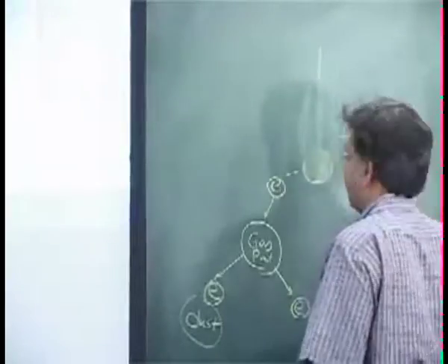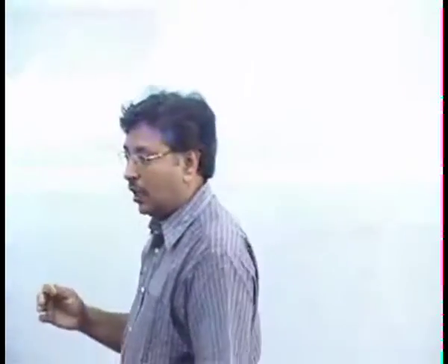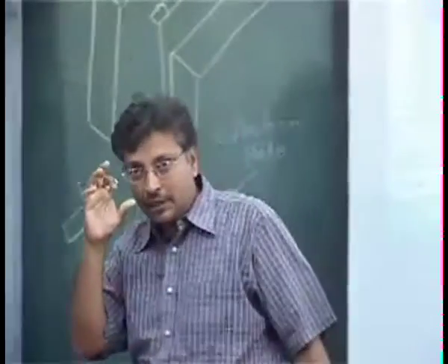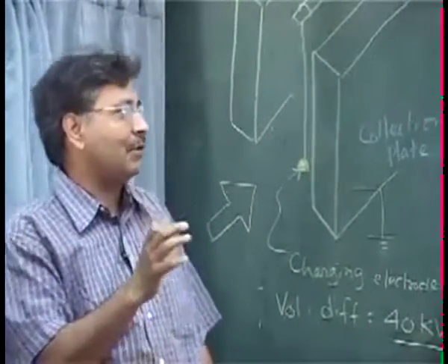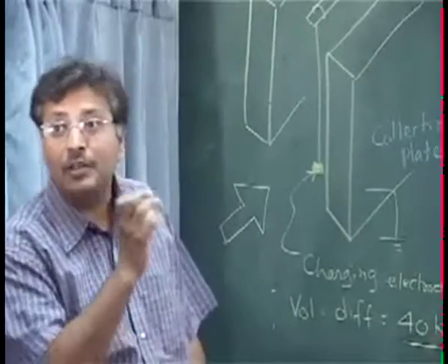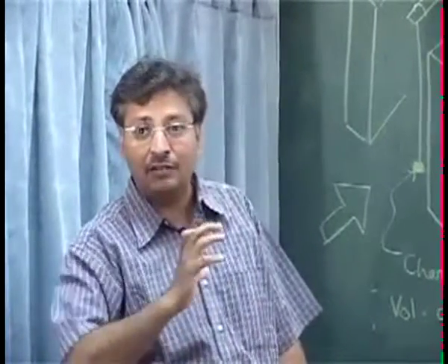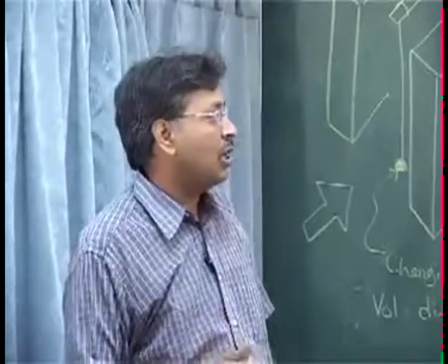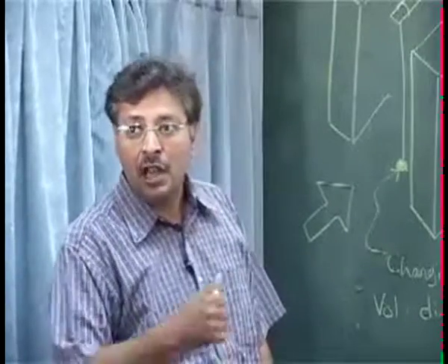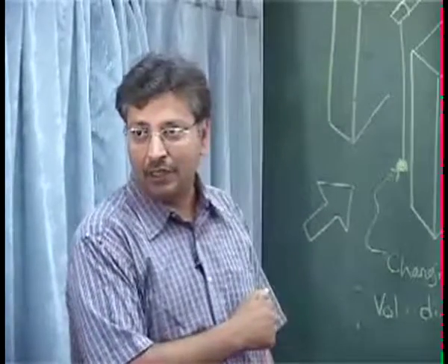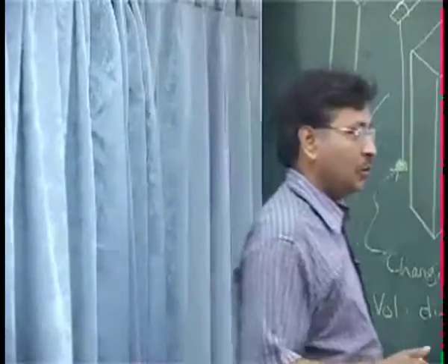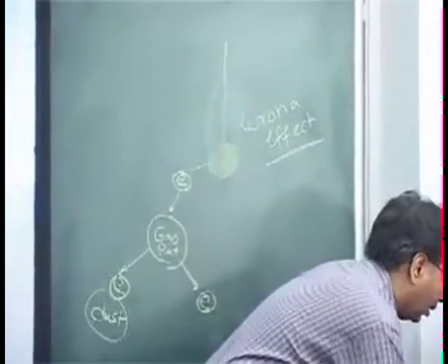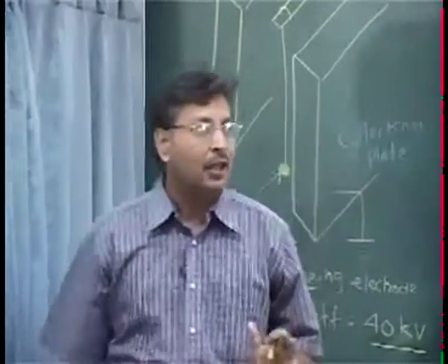Some of the ESPs, at least some of the experimental ones, have this kind of glass that you can see through, and you can see the corona being generated, and that corona is key. If the corona is not being generated, it means your ESP will not work, because you are not producing enough electrons to sit onto the particles and drive them towards the plate. So this is the mechanism, or the physics if you like. Then there is mathematics for this that we probably will not see in much detail, but I want you to get the sense of the thing.